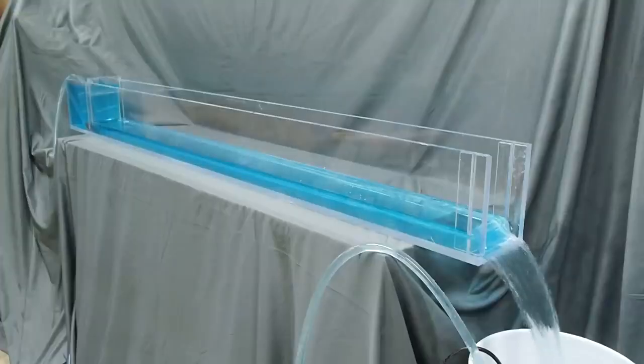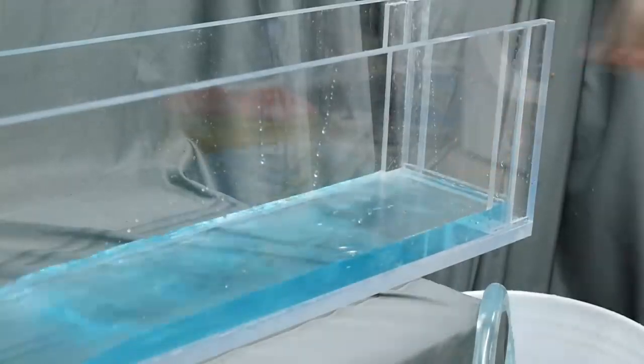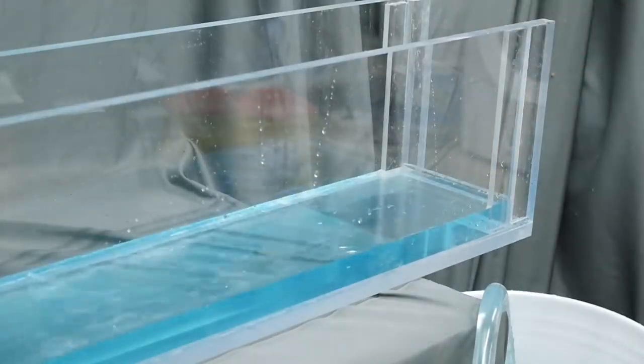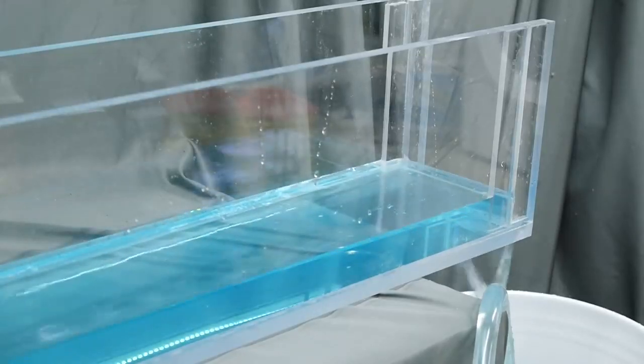If you watch my previous video on the basics of open channel hydraulics, you'll remember that for subcritical flow, that is, slow, tranquil flow seen in most rivers, the depth is controlled by downstream conditions. That means adding a weir across a river will increase the water level upstream. But by how much depends on the flow.